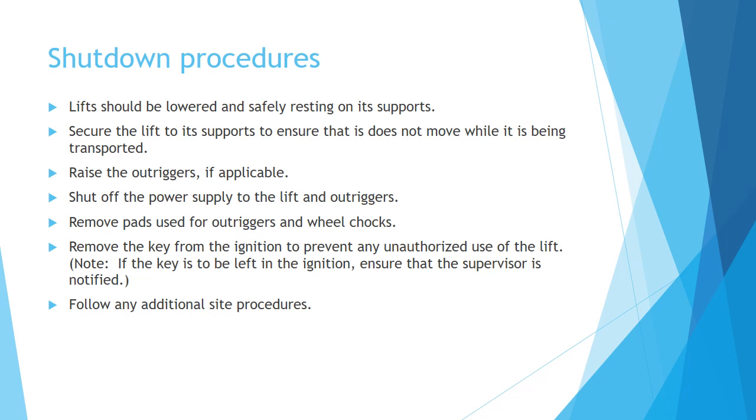Remove pads used for outriggers and wheel chocks. Remove the key from the ignition to prevent any unauthorized use of the lift. Note, if the key is to be left in the ignition, ensure that the supervisor is notified. Follow any additional site procedures.